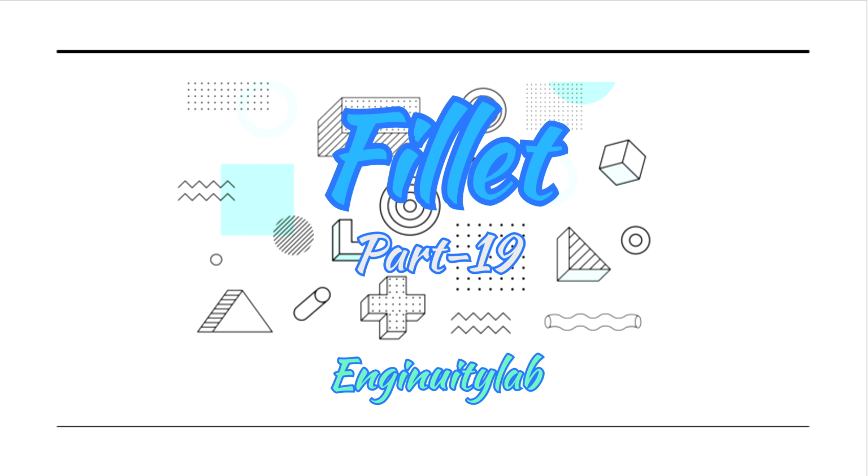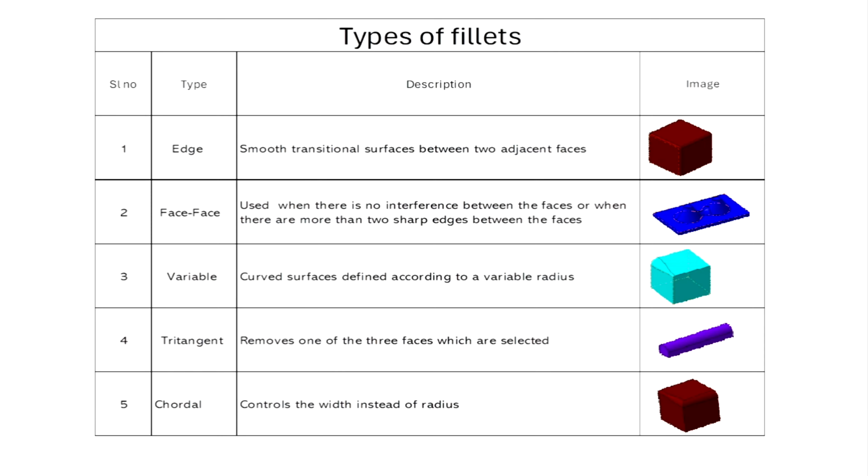This video helps you to deep dive into one of the most used tools in CATIA modeling, the fillet feature. Let's get started. Fillet. A fillet is a rounded interior or exterior corner applied to solid edges. Fillets improve aesthetics, reduce stress concentration, help in manufacturability, and allow smooth assembly fit. In CATIA, the fillet command gives you several variations and advanced options depending on your design needs.